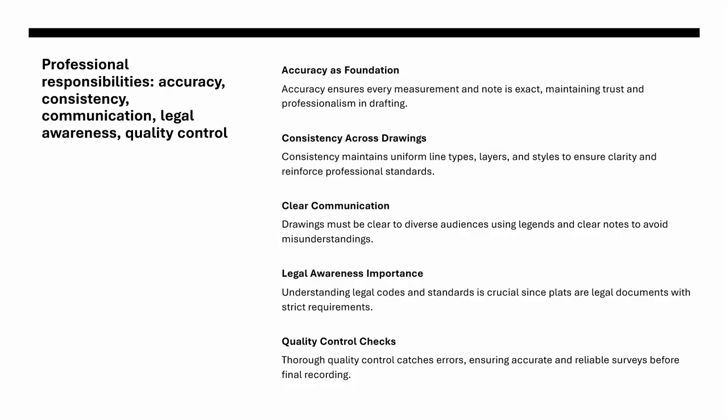Third comes communication. Your drawings must be readable and clear to people who were not in the field and did not collect the data. Think about who looks at a plat. Engineers, attorneys, judges, clerks, landowners. Many of them will not understand survey jargon. If the drawing is cluttered, if notes are vague, or symbols are not explained, then the plat has failed in its purpose.